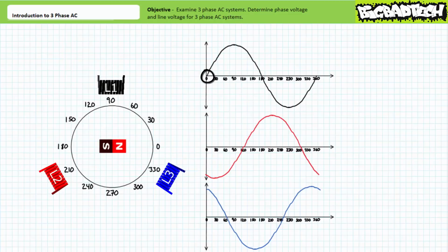In summary, voltage across winding L1 crosses zero, going positive at 0 degrees. It experiences a positive peak at 90 degrees, crosses zero, going negative at 180 degrees, experiences a negative peak at 270 degrees, and crosses zero, going positive at 360 degrees or 0 degrees, and the process repeats itself. In between these key moments, voltage rises and falls as would a sinusoidal function of angular position. Voltage across windings L2 and L3 exhibits similar behavior, only the peaks, valleys, and zero crossings are shifted.